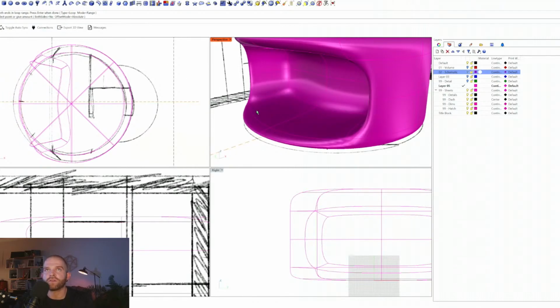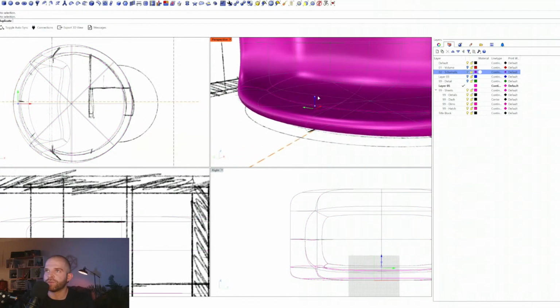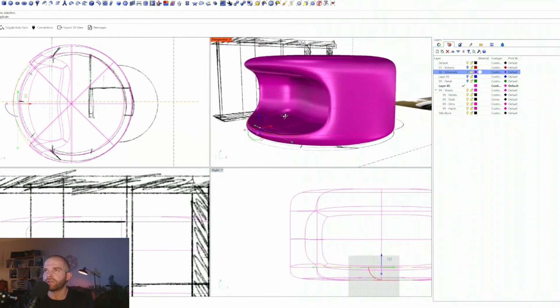Actually, I'll activate the option for both sides. So if I do this edge and I have both sides on, which I believe I do now, yeah, it's creating a cut. I want to just hover over it, but it moves away when I do. But it's creating an edge loop on both sides of this orange line. So I can have one closer to the edge, just like that, and have one follow shortly after. Now if I select this new edge, I can move it up. There we go. Get a bit more solid. I actually like this organic look.